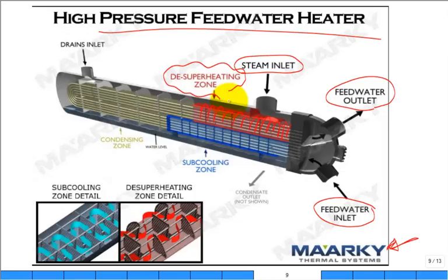There you go. All right, de-superheating zone. And then they have this condensing zone. So basically I would think that right here the fluid is saturated vapor. As it's going this direction, comes around, right there it's saturated liquid. And then they could even have a subcooling zone.